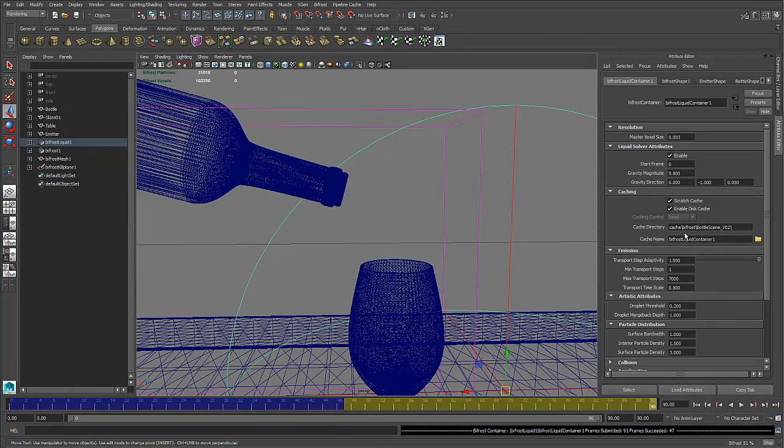The other thing I can do is create a mesh and bake that mesh out. If I go to polygons here, I can bake that mesh out as an alembic. So if I switch to rendering, just next to Bifrost there's a pipeline cache option. If you click on that, you've got the alembic cache. So once I've brought my cache data back in, I can take my mesh and export it out as an alembic file, which gives me even greater levels of efficiency and control.